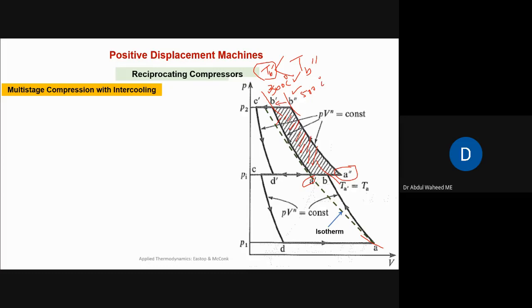You have learned about this effect in the gas turbine chapter, but we could not discuss it in such detail there. For that we have to show it on a PV diagram. Right? So I think now it is clear why intercooling with two-stage compression reduces the work input.